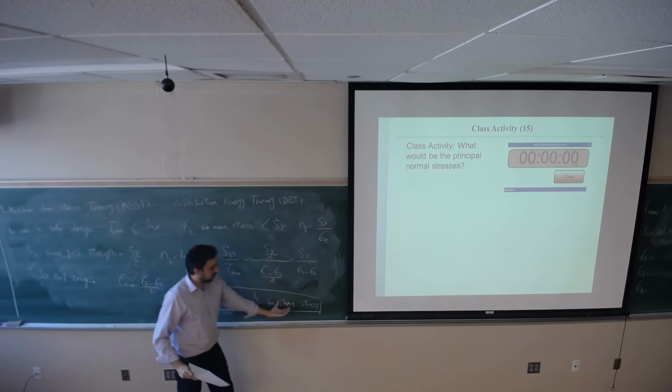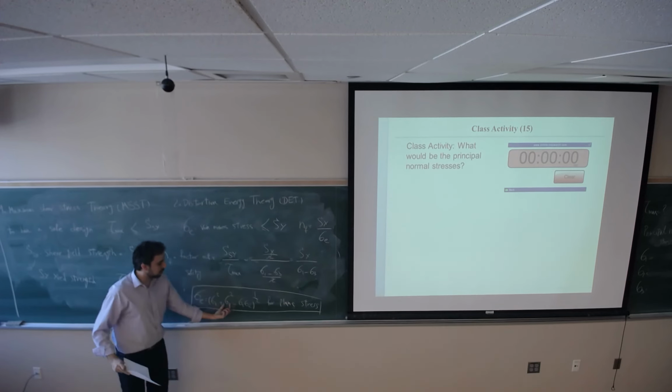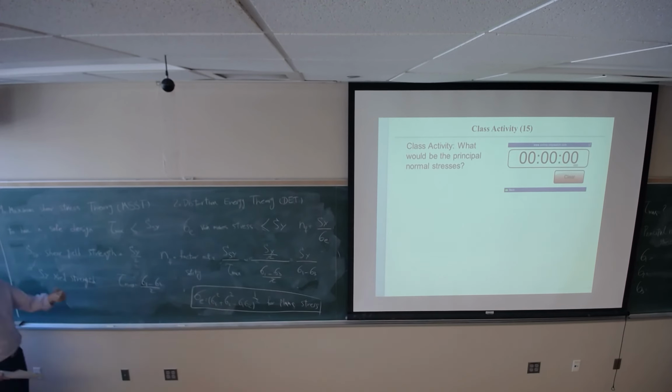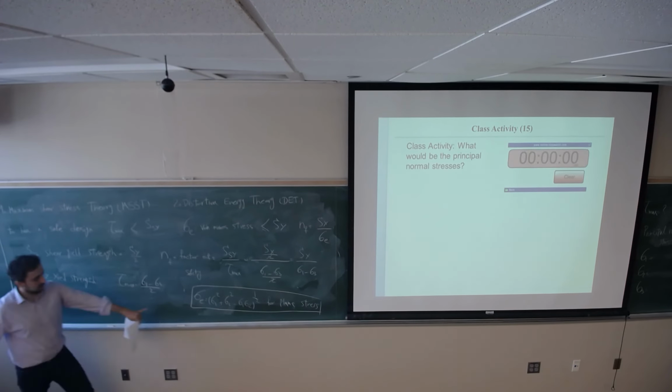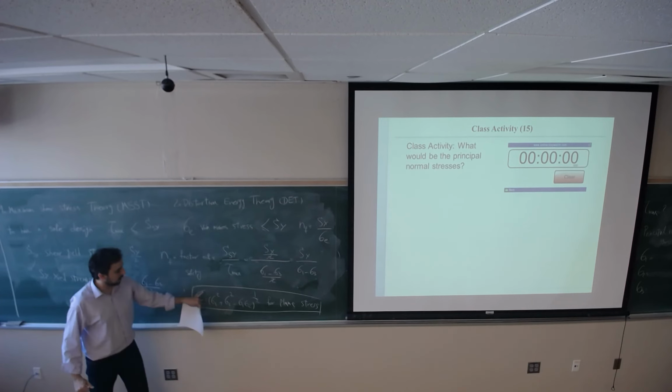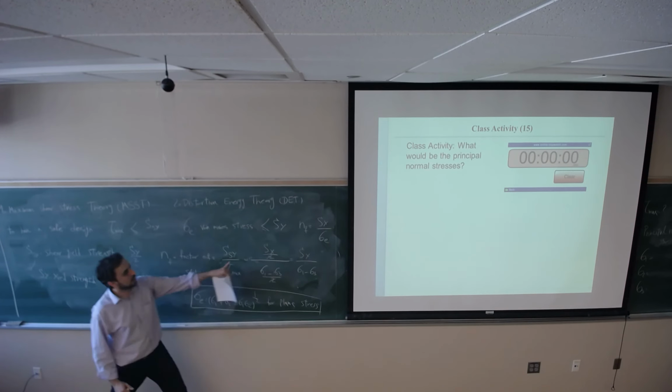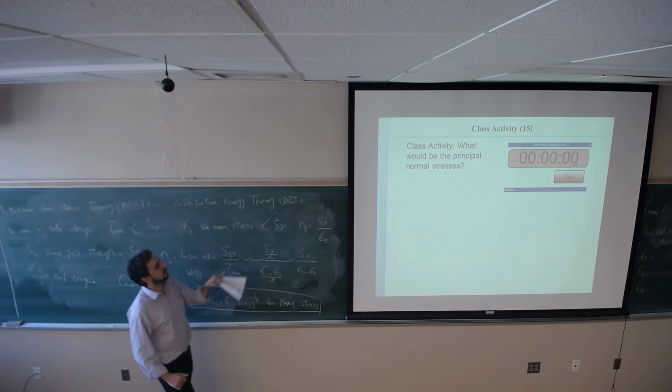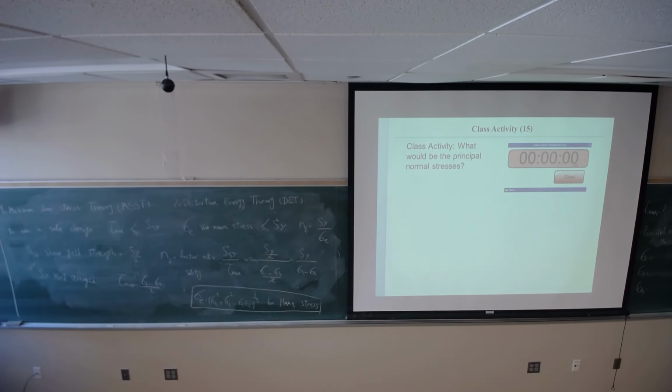If you have plane stress, you have two principal normal stresses showing up, sigma 1 and sigma 2. This equation is going to give us one value, and we compare it with SY, and we can say if the design is safe or we are going to have failure.